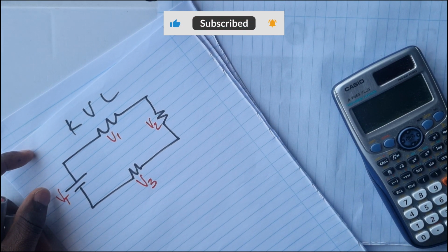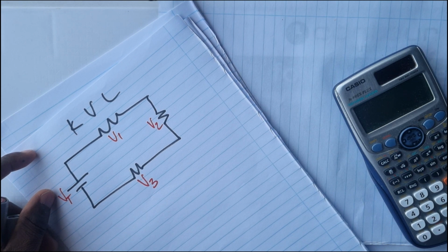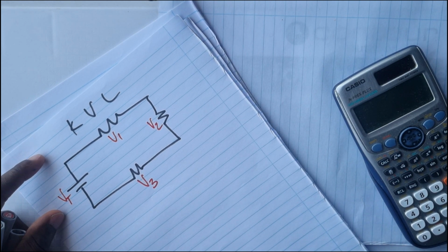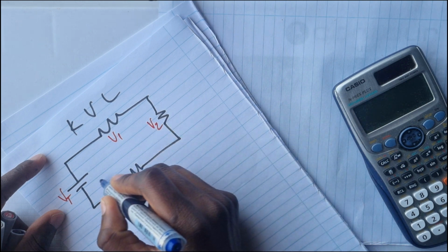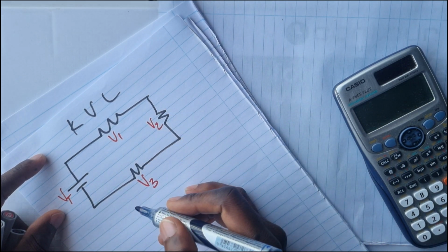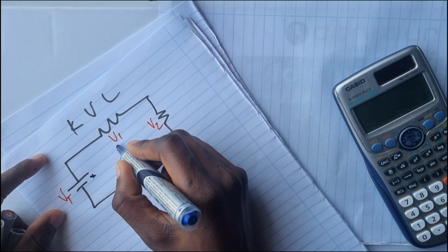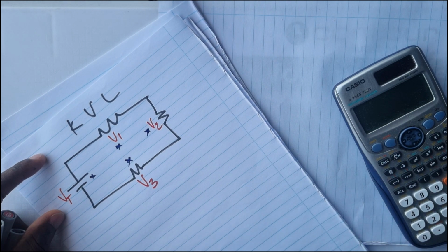Now, Kirchhoff's voltage law. Kirchhoff's voltage law states that the algebraic sum of the voltages in a closed loop must be equal to 0. So that can be explained using this simple circuit. The algebraic sum means that the voltages that we have in this closed loop must give us 0. So this voltage plus this voltage and this voltage and this voltage must give us a total of 0.